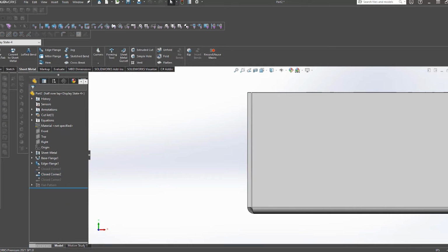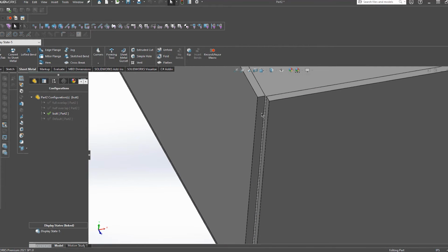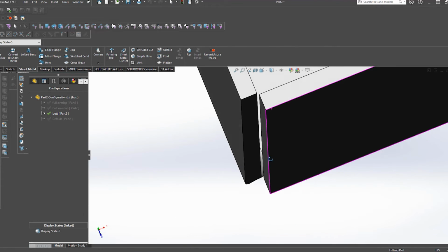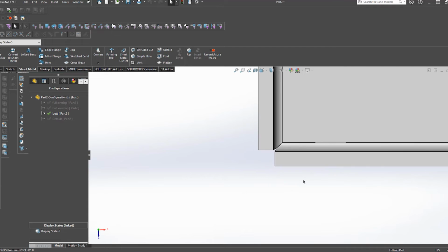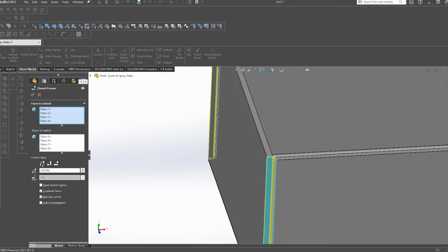So the last closed corner type that I'll go over is called the butt. In this type, the corners do not actually overlap at all. They butt up together so their edges are right next to each other. If your design will include welding, I don't recommend choosing this closed corner type unless absolutely necessary. Full overlap and half overlap are much better options if you're going the route of welding. So that covers the three types of closed corners that you can create in Solidworks.